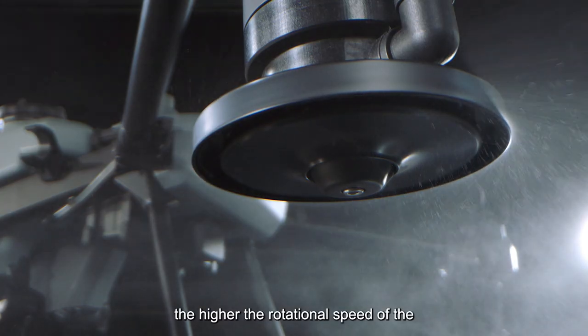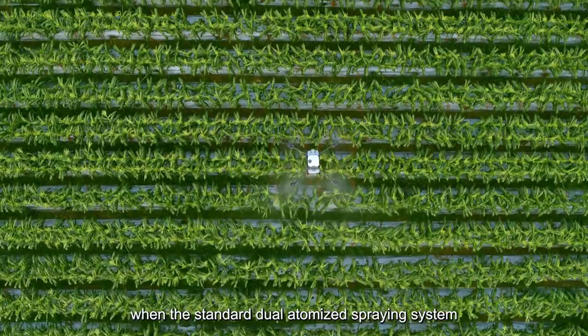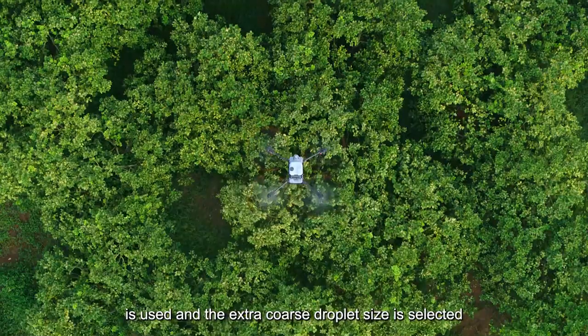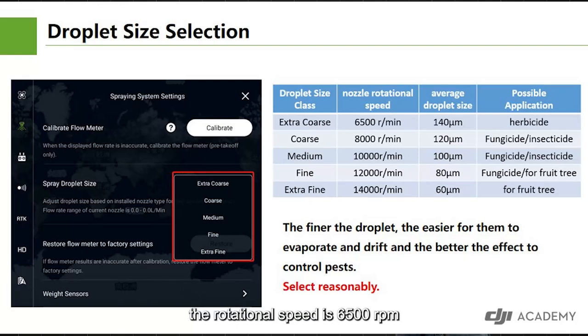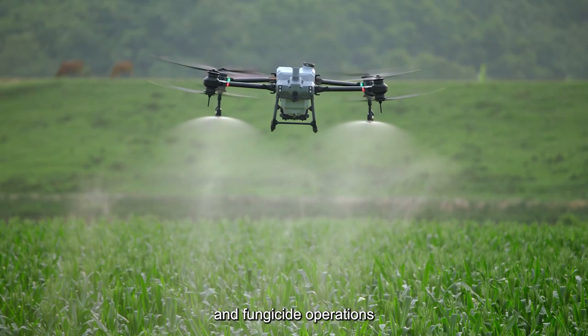The higher the rotational speed of the centrifugal spraying system, the finer the droplets. When the standard dual atomized spraying system is used and the extra coarse droplet size is selected, the rotational speed is 6,500 RPM and the average droplet size is 140 microns. When the extra fine droplet size is selected, the rotation speed is 14,000 RPM and the average droplet size is 60 microns. It should be clear that, under the same liquid amount per hectare, the finer the droplets, the larger the number of droplets, which is conducive to improving the effect of insecticide and fungicide operations.